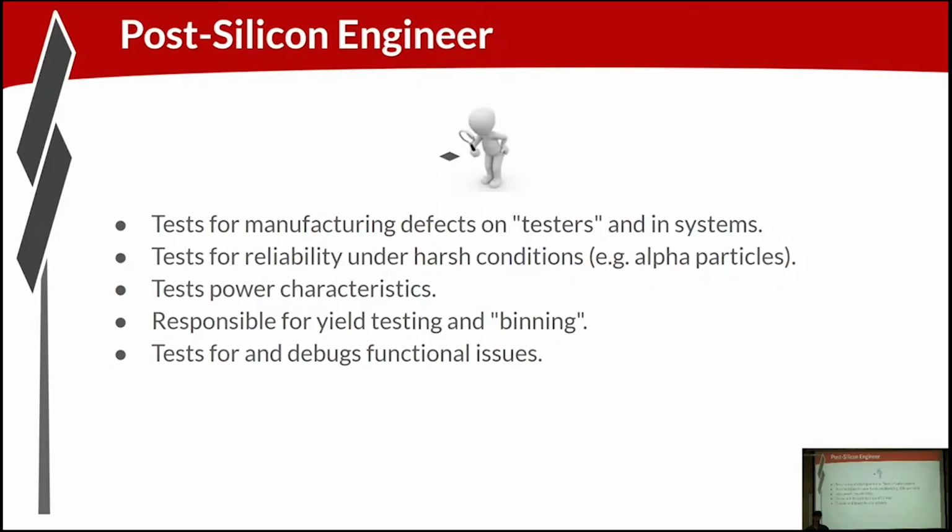And also the clock speed of the chips, right? So we'll crank up the clock on these parts and see where they fail and then back off a bit and bin it appropriately into a particular clock speed bin, right? So over the years, over the course of my career, the binning strategy has gone from no strategy, it's one chip, it's one product, to an incredibly complex binning strategy that involves multiple people to sort the whole strategy out alone, and then, you know, more engineers to execute on that strategy post-silicon.